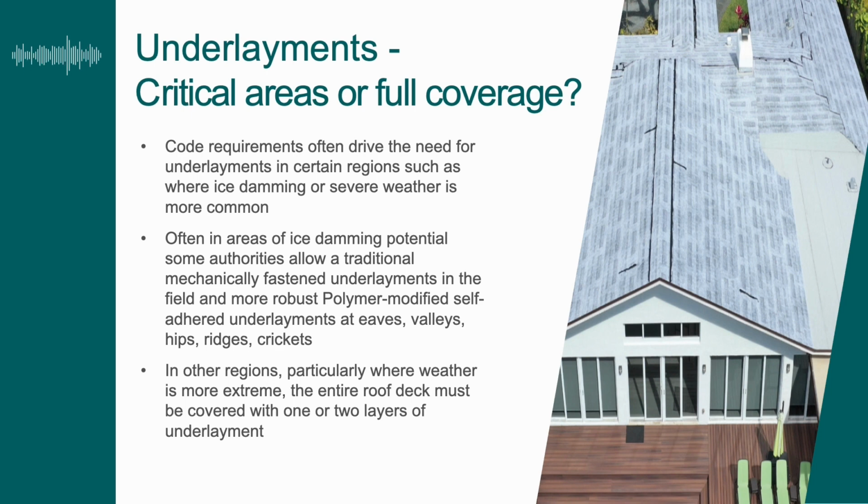In some areas, code mandates, like I said before, just those critical areas to have the self-adhered polymer-modified underlayment. And in other regions where you have hurricane zones and other severe weather events, sometimes even two layers of underlayment are necessary and mandated by code.